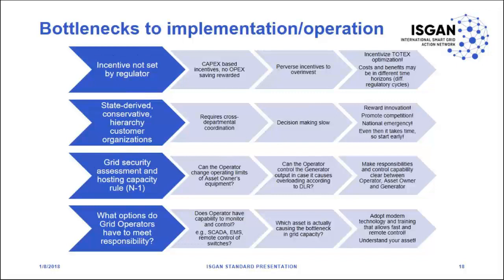So, if there are so many obvious benefits to dynamic line rating, why is it not more widely used? Actually, many grid operators already apply some form of flexible rating of their power lines and substations. It might be that they use ratings that vary between seasons, like winter rating and summer rating, like Jean-Louis explained before, or by ambient temperature, what is called an ambient adjusted rating. But these methods still underestimate a lot the additional capacity that actually exists.